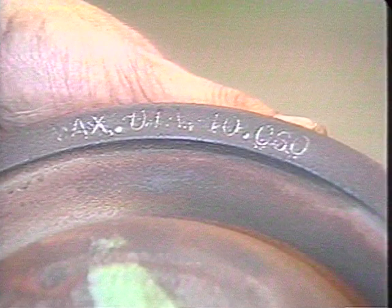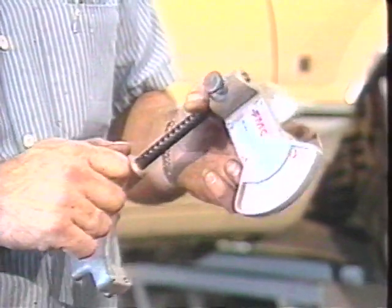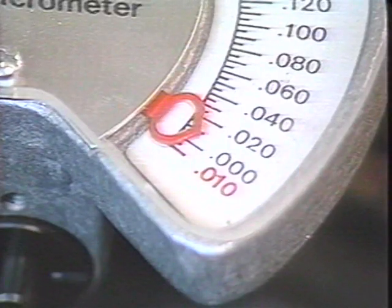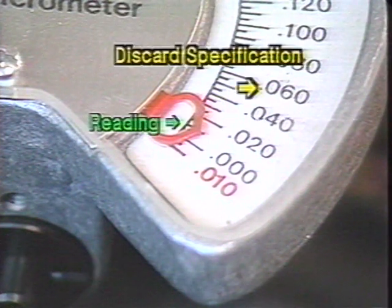To service a brake drum, locate and record the drum's discard specification. Determine the drum diameter and set the drum micrometer to indicate this reading. Place the micrometer inside the drum. Read the number indicated by the pointer. Mark the location of your reading, then check the drum at several different locations. Different readings indicate an out-of-round condition. The highest number that you read must be compared to your discard specification.